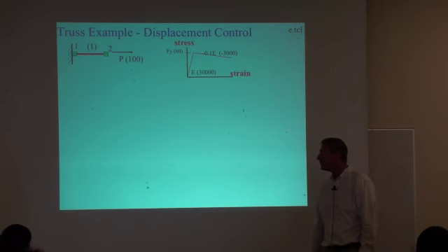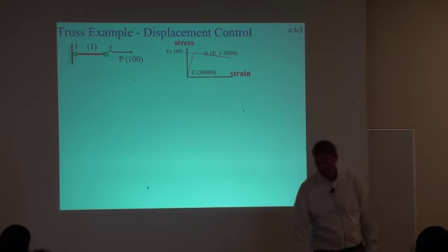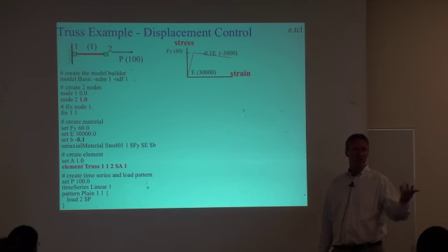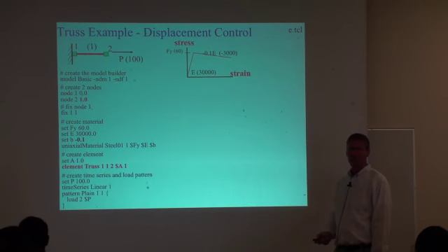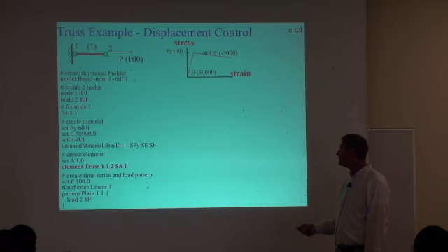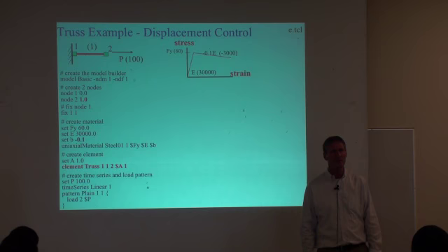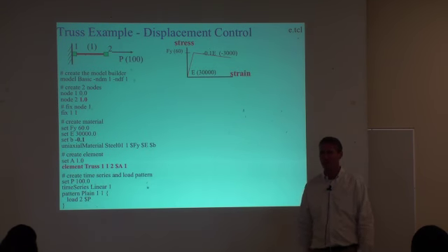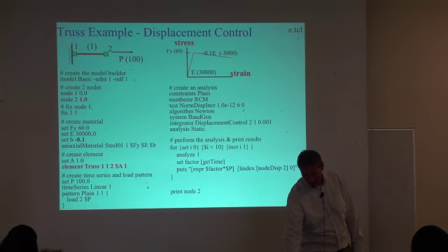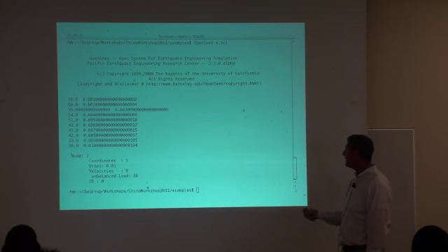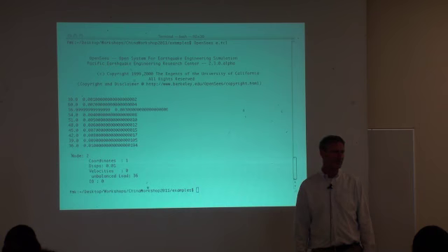Okay, I'm going to do the same example. All I'm going to do here is use a different type of element. We're going to use a truss instead of a zero length element. That's the only difference between this model and the previous model. So what changes do I have to make? Well, the truss needs some length, so I'm going to specify node 2 to be at 1.0. Instead of a zero length element, we use the element of type truss. It takes 1, 2, $A, and 1. The arguments for the elements are a little bit different. The other change is to move the node out 1. So that's the difference between the two scripts. If you understood the previous script, you understand this script. We do all the same things, and hopefully if you compare to the previous one, you'll see the answer is identical.